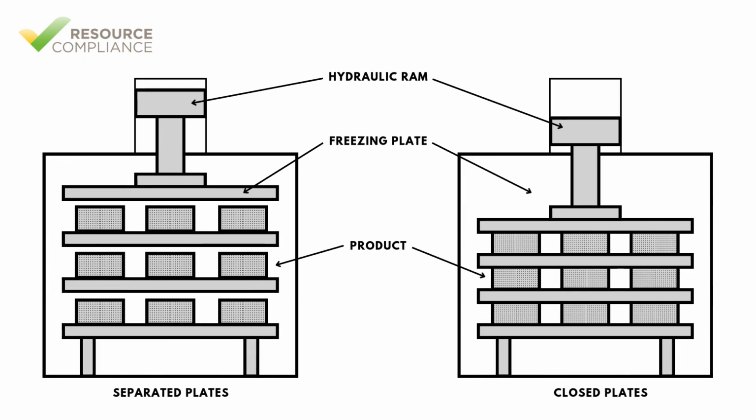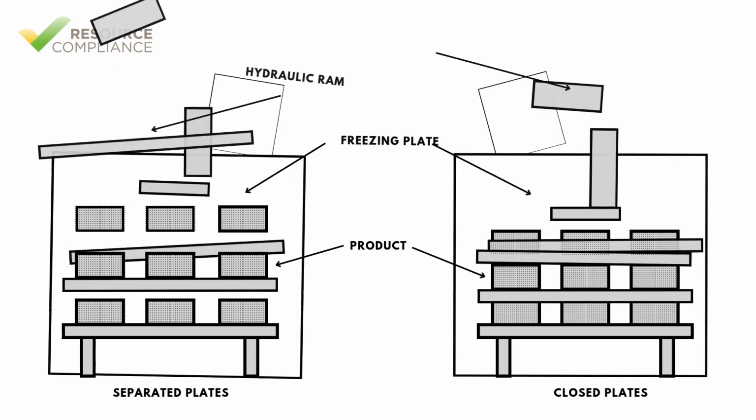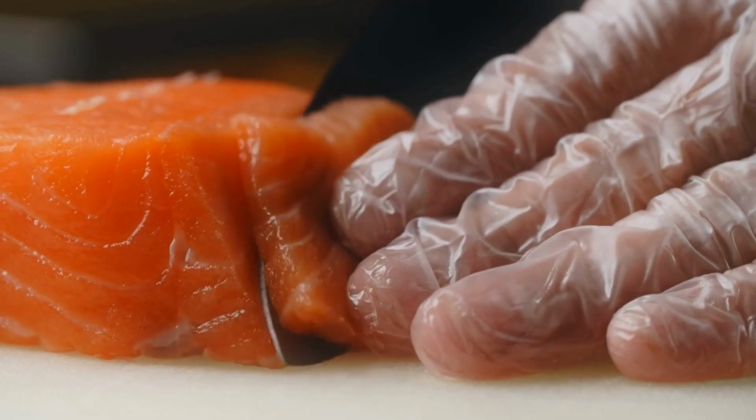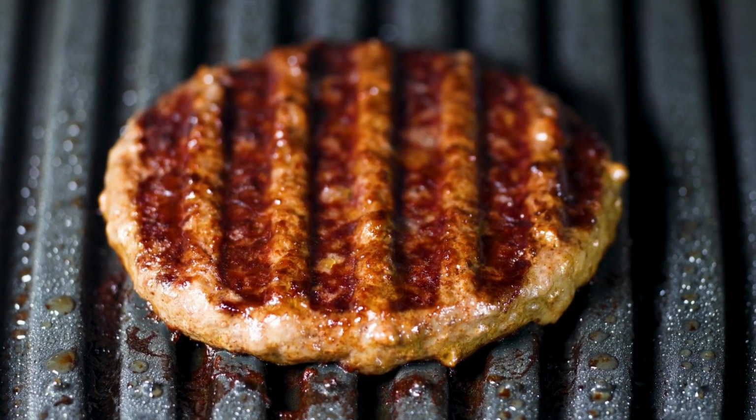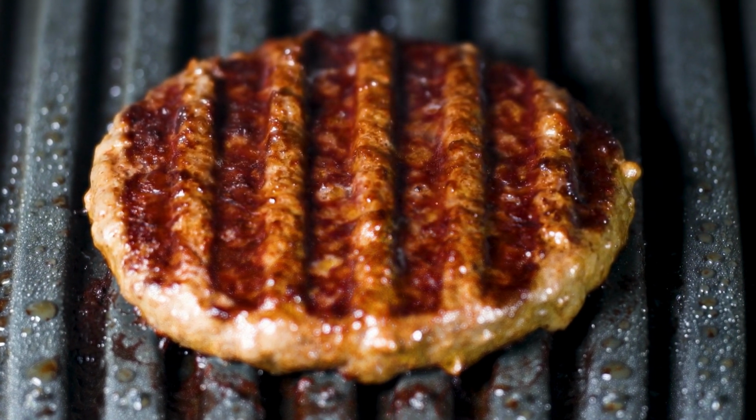In a plate type freezer, products are placed directly between or onto cold metal plates. The refrigerant circulating inside the plates absorbs heat from the product through direct contact, rapidly lowering their temperature and freezing them. Because the freezing occurs via direct thermal conduction, the process is highly efficient, ensuring fast and uniform freezing. The plates can be hydraulically or pneumatically pressed to improve contact with a product, enhancing heat transfer. Plate-type freezing evaporators are used in the meat industry for freezing fish fillets and beef patties, but are also employed to freeze packaged foods, such as ready-to-eat meals and frozen juice concentrates.